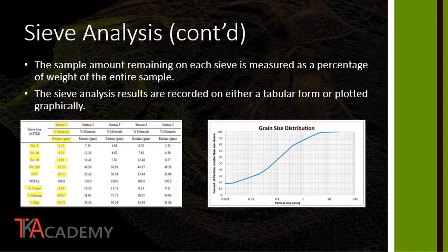Another example, let's look at station number 3, sieve analysis. Again, percentage of material, the amount retained measured in grams. So on the number 8 and 16, we had 4.89 and 6.82 percentage that was retained on those two sieves. That equals the coarse material in that soil sample as 11.71.